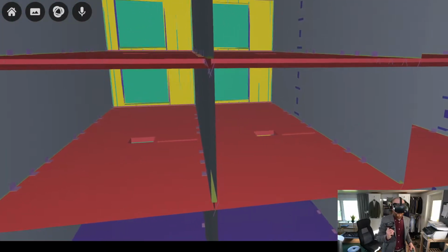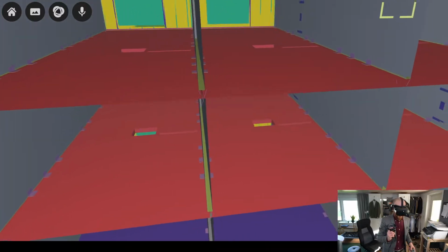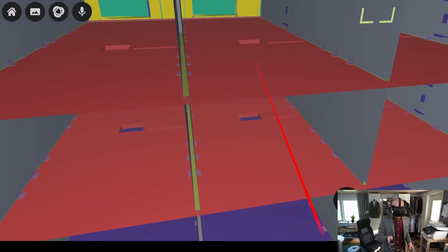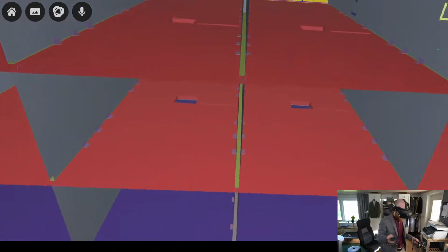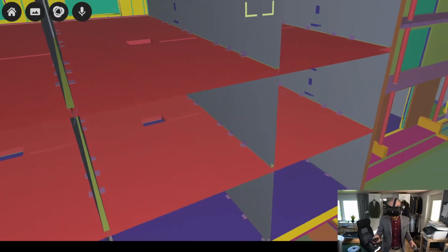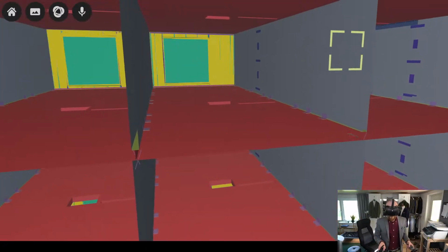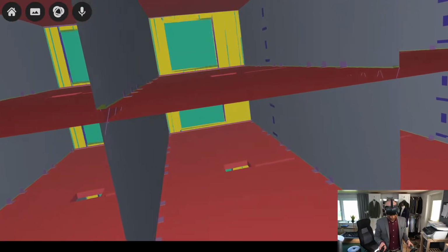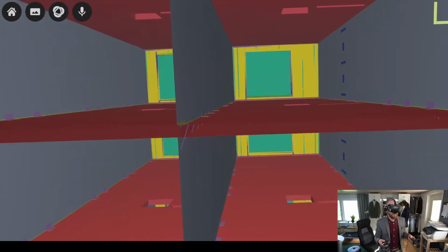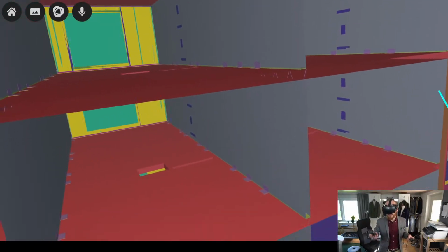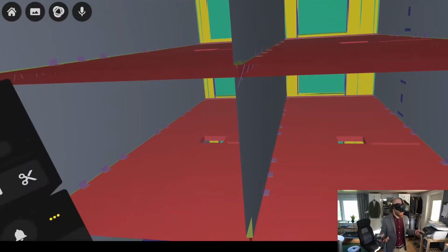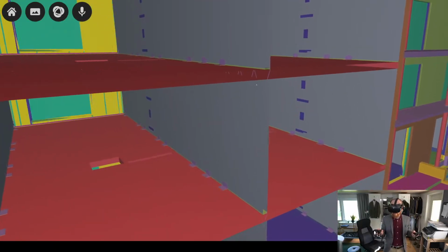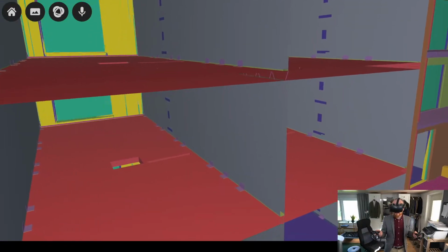If I go up a bit, I might be able to show you one of the CLT plates, a second one, and so on. So every two apartments you get a new CLT plate. And what this means is that you get a more effective mounting process at the construction site. The crane doesn't have to lift as many CLT elements when you're raising the building. Erecting is probably erecting the building. You'll get a faster process with the crane.